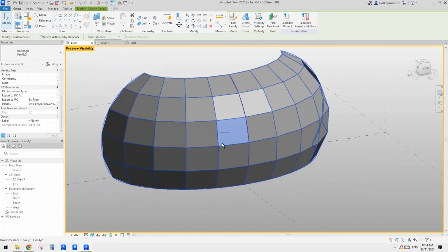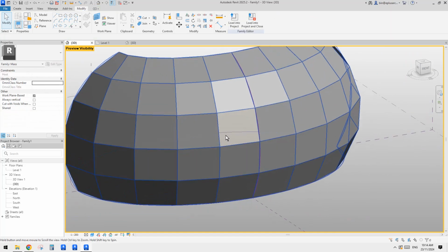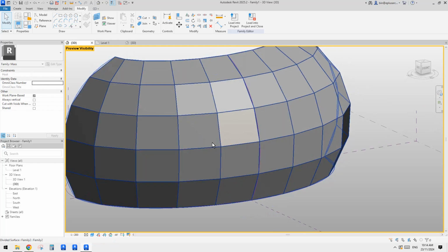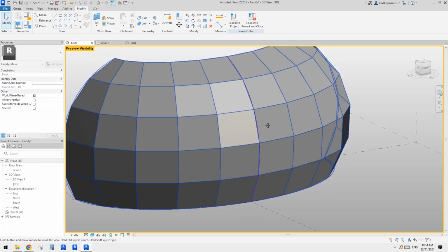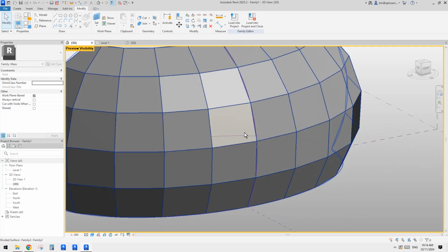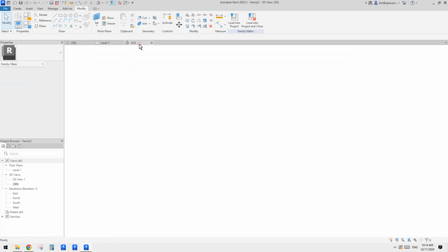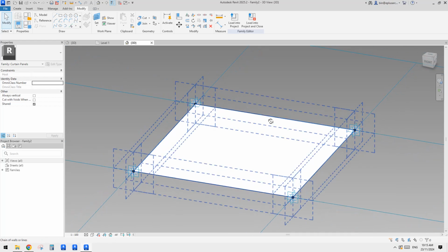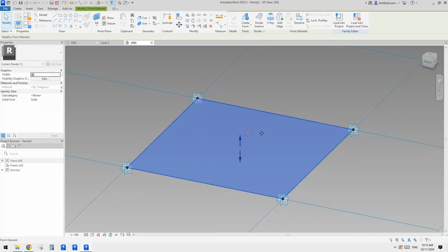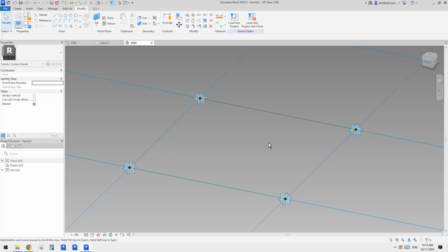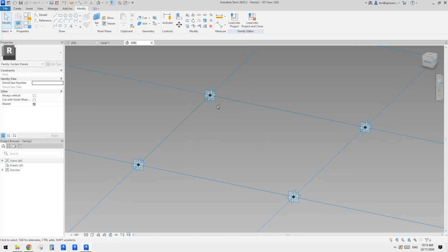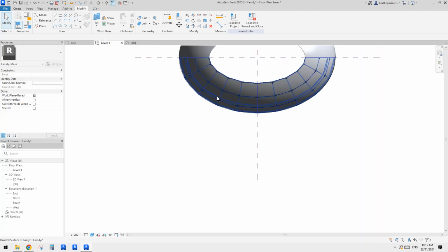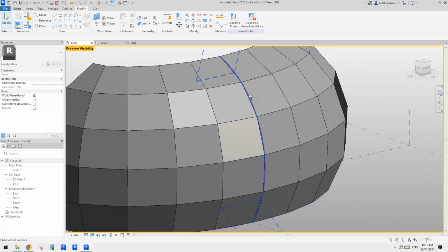All right. So instead of using an adaptive family, which requires us to place one and repeat, a pattern-based family is more straightforward, so it automatically places onto a pattern. Okay, so that's fine. So now let's try and see if we can create this surface. Looks the same, but when we place onto this divided surface, it creates a curved shape.